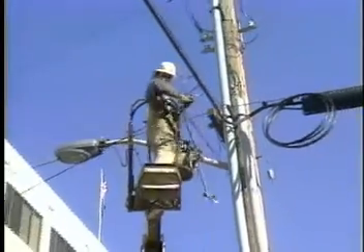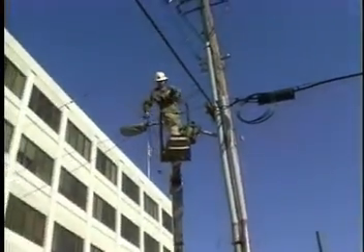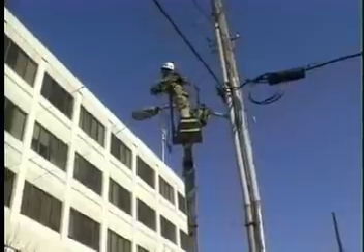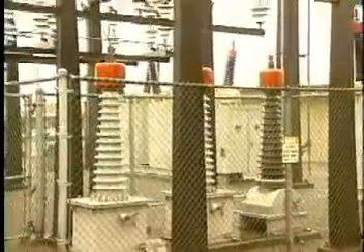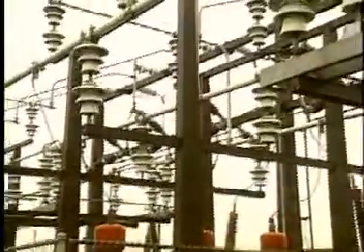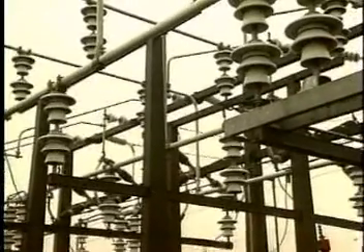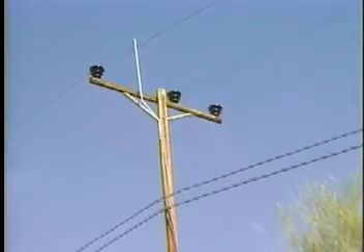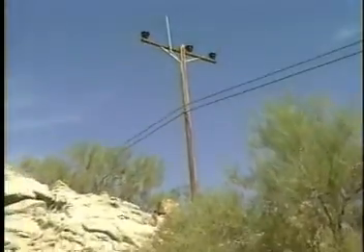Even though fiber optic cables may be all dielectric, a static charge can build up on the cable's surface when close to high voltages. Water evaporating from the cable surface will leave conductive residues that encourage scintillation, a surface arcing that can damage cable and cause injuries. Scintillation mainly occurs near cable attachment points and can be reduced by proper bonding to ground at regular intervals along the route.